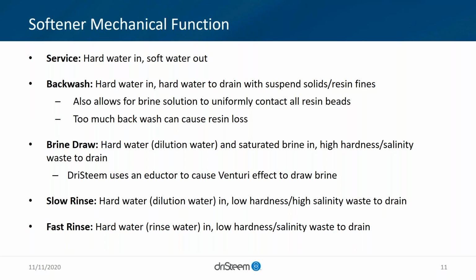And how that's drawn into the system is essentially a Venturi effect. As you drive one side of the water pressure across it, it's going to suck it and pull it up, go through that resin bead and reverse that reaction.